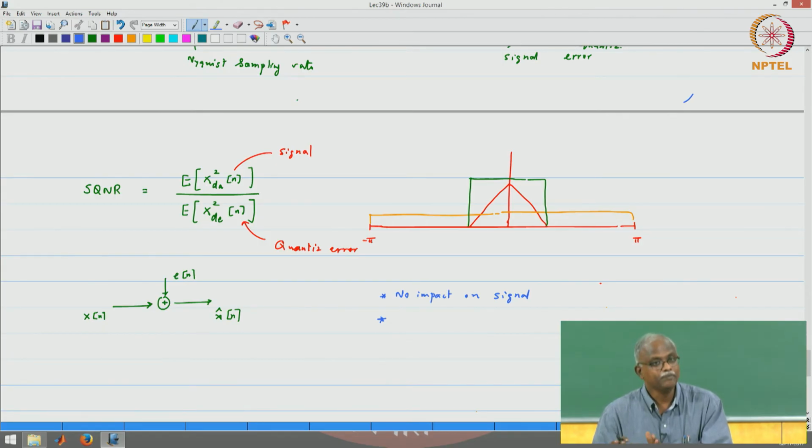Look at the spectrum. How much of the noise power is outside of the band of interest? In other words, you have basically retained 1 over m of the total noise power. In the context of the previous time when we discussed oversampling, it was only to reduce the complexity of the analog anti-aliasing filter, but now you see that you actually obtain more than that. You can now go through and show the following result.